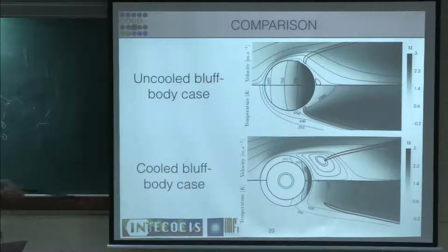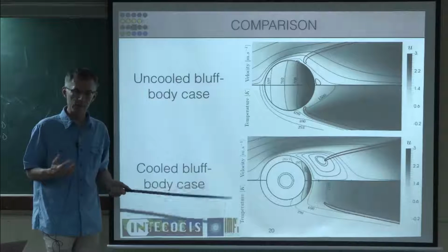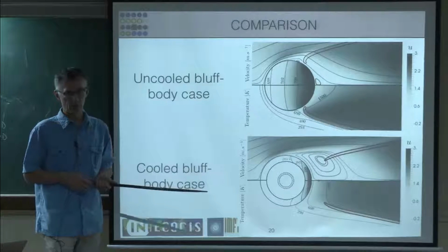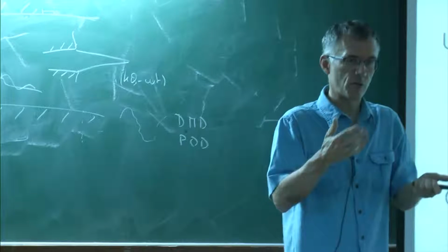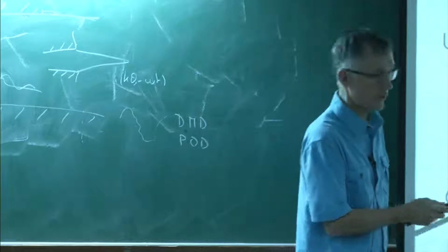So this is a comparison of the 2 flames. They are very different. And again, it's a striking result because in most models, we don't care about the temperature of the flame holder. Actually, when you write FPI, you write a tabulation, you start by saying, this is not important. I don't want to know about it. Well, in practice, it's changing things.